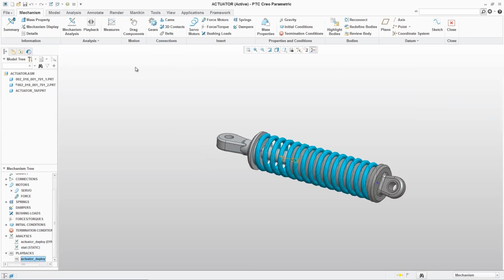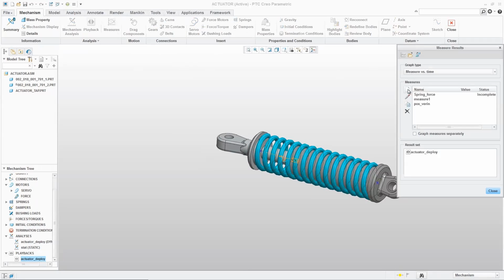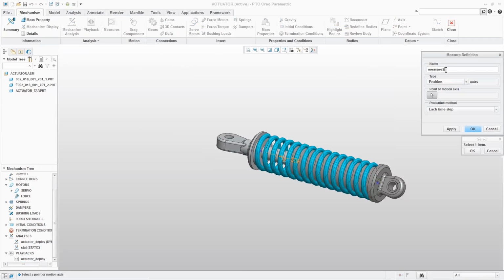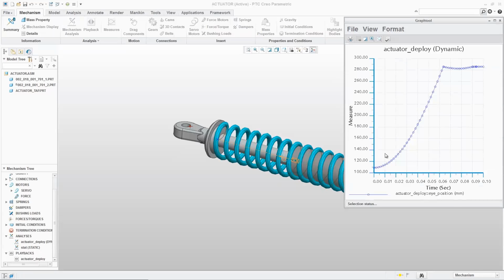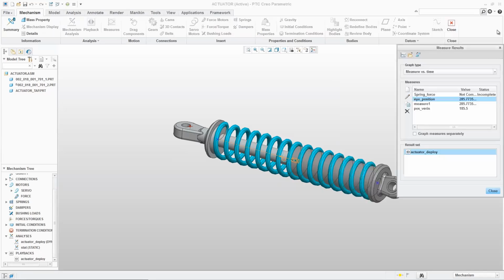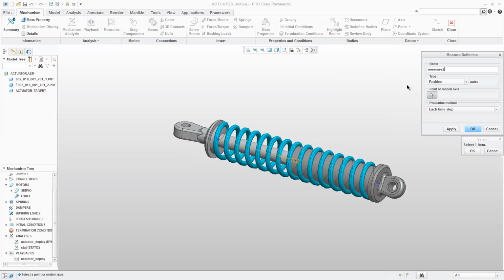And once we have that playback, you can go through, you can see any time slice, slow it down, share off an animation of that. And we can still use our analysis to take different measurements as well. So we can go through here and look at the position, for example, if we're interested in that. But now with the new spring system, we can see how that measurement changes, taking into account the new forces that we're working with. So looking at the graph here, we can see the initial uncompressing is fairly non-linear now, and we can see that it bounced back at the end of the cycle there as well. And then the end is going to settle out into that steady state. Right. So with that, we can go ahead and move on and do the same sort of thing, but instead of position, maybe now we want to take it to loads.